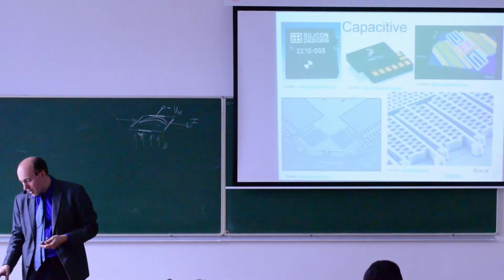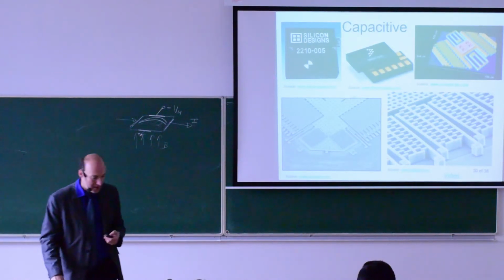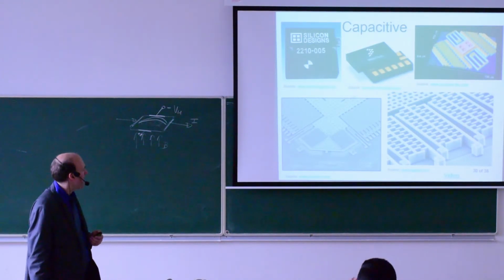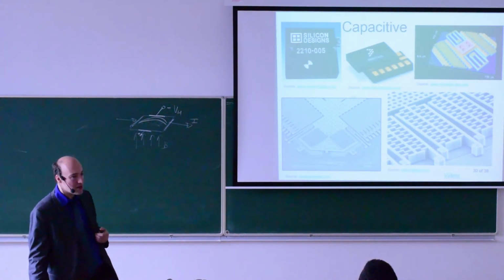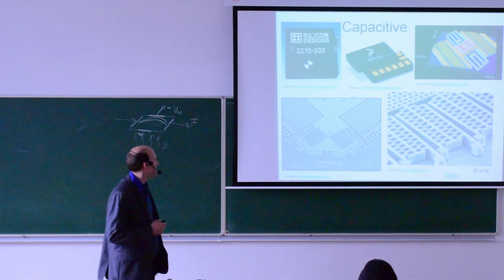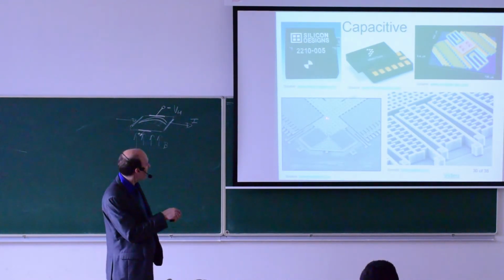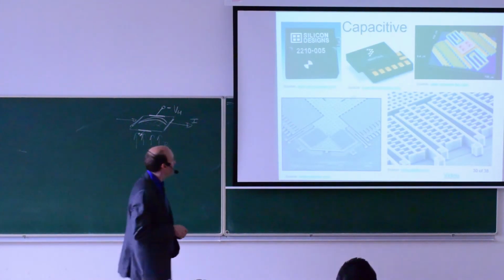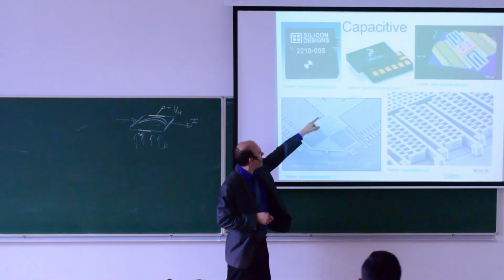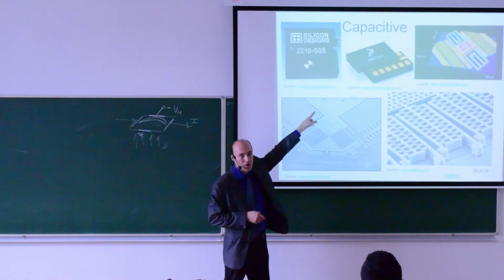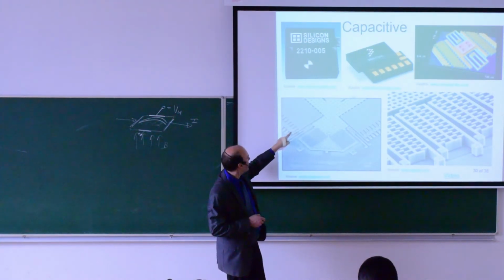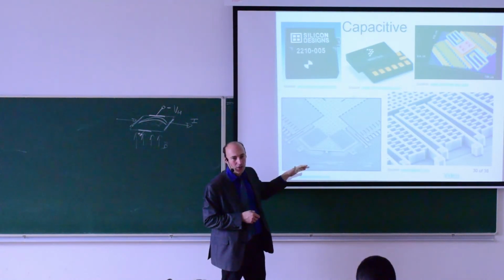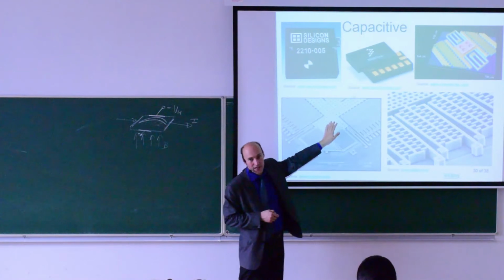Today's accelerometers are based on silicon, and they are micro-manufactured with the same or similar technology as integrated circuits. What you see here are some examples. In this picture you see a seismic mass that is moving. The electrodes attached are this one, and so forth. There are multiple electrodes connected together, and these are the electrodes that are connected to the frame. So this is a 2-axis accelerometer.